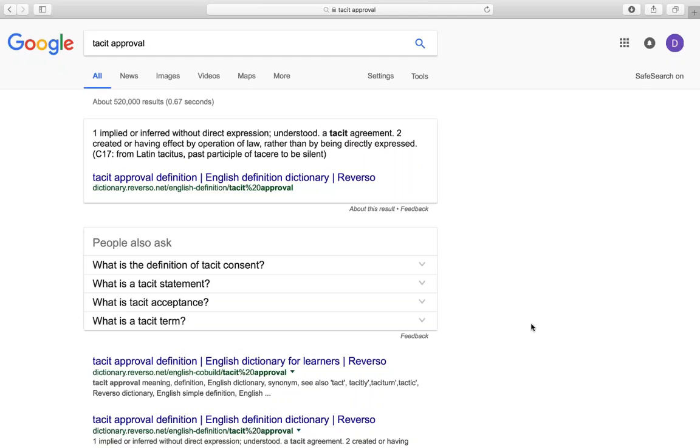Dealing with at-risk behaviors affects everyone on the site, not just workers taking risks. But when we find somebody whose behavior is too risky, what are we going to do? We're going to stop the worker without startling him or her. We take the worker aside, speak to him or her, and express our concern for their safety as well as that of co-workers. State what action or behavior was incorrect, and explain why the action or behavior was incorrect or at risk.